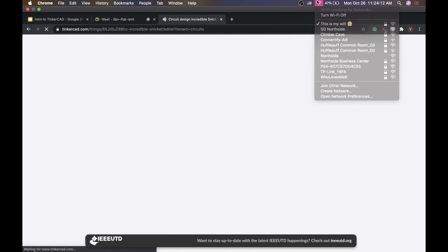And I'm also going to connect the analog pin 0 over to the middle pin for this. And I'm just gonna make that blue. I'll wait a second because of the buffer, let y'all see how it's wired and let y'all do it. And then I'll start writing the code for this and I can demo it for y'all.